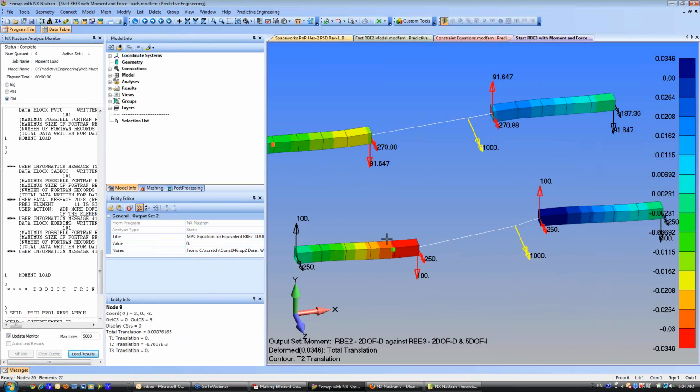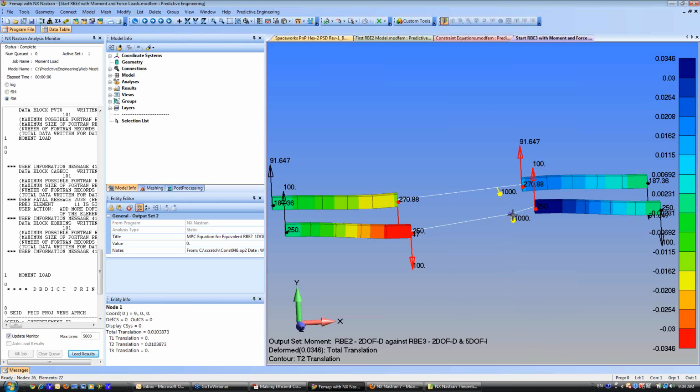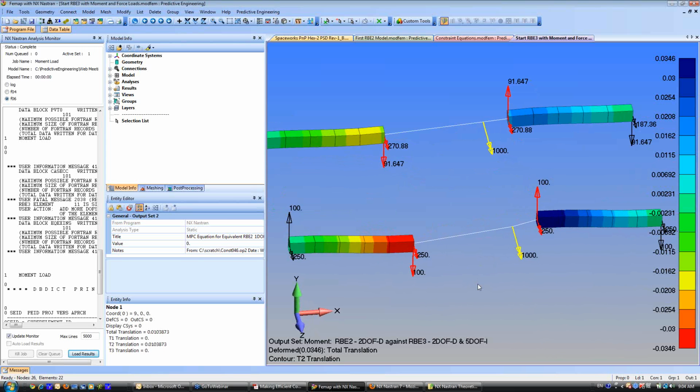And what it means is that if you think of this as a structure, you could go through the rigid body motions and say, well, we have this pinned at 1, 2, and 3, so that takes care of the translational. Now let's go through the other 3 rotational. Well, around the RY, that's addressed by the translation at both ends.